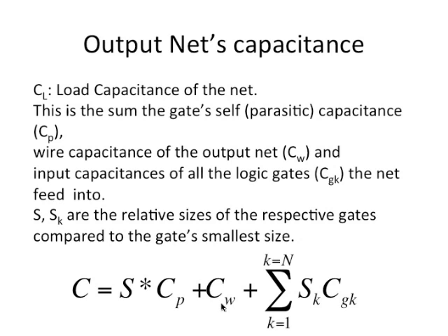And then you have the wire capacitance, because here we are talking of the capacitance of the net, which is the output of the gate. So that consists of the self capacitance connected to the net, then the parasitic wire capacitance, and then the gate capacitance of all the gates it's connected to. Here there could be n gates. Usually you don't want n to be too large, right? Maybe 4, 5, 6. Remember we said fan out 4 sizing. So we don't want too much of a spread.